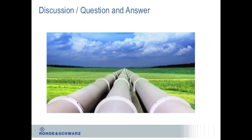Well, EVM is error vector magnitude. As you're probably aware, in transmitting data in LTE, there are 3 different MCSs, modulation encoding schemes. There's QPSK, which is 4 symbols. There's 16 QAM, which has 16 symbols, and 64 QAM, which has 64 symbols in the downlink. In the uplink, right now, you have QPSK and 16 QAM.